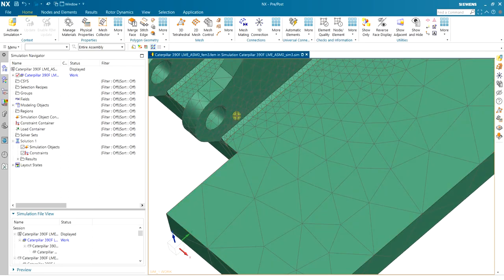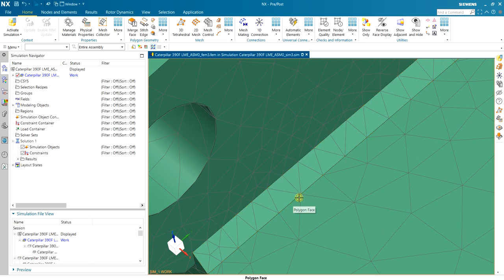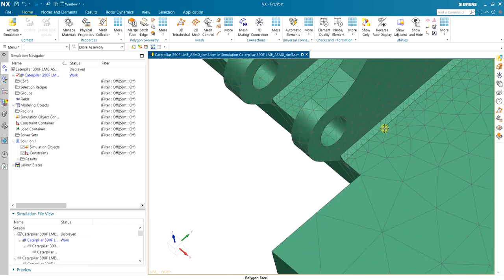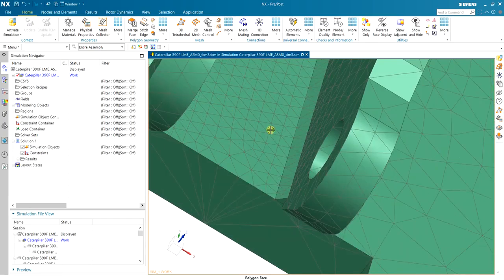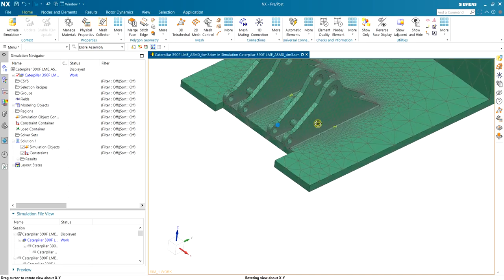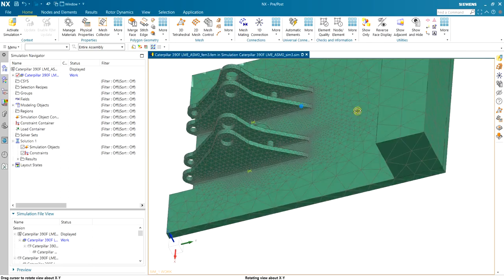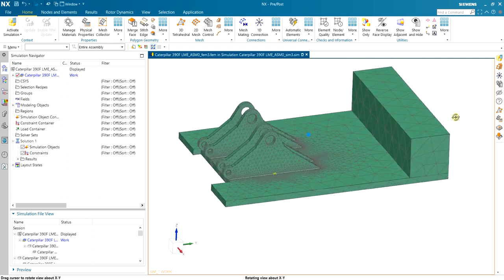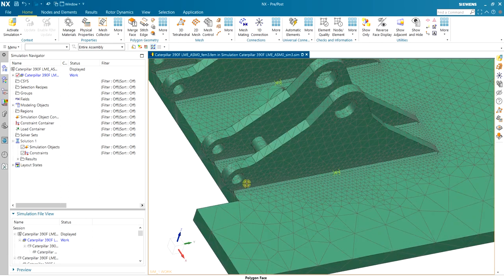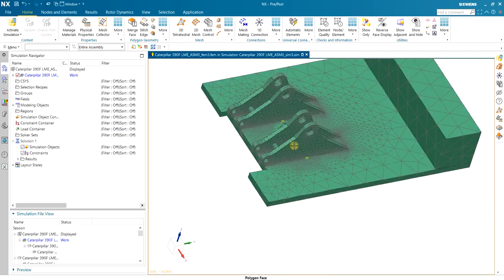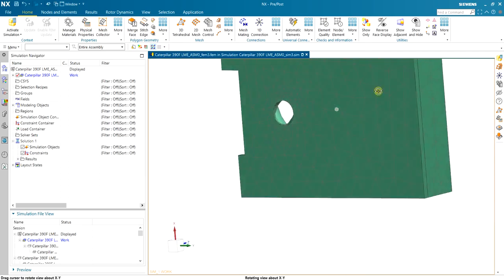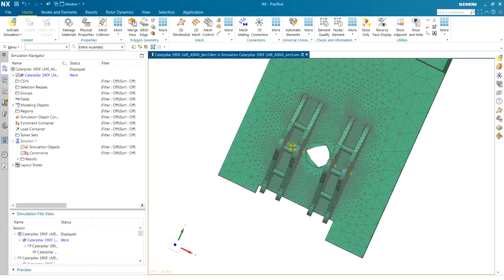Now you see that near the places that we needed mating, the elements are aligned to share a node, so the mesh can mate on each face. And also the size remains big for the parts that we don't need much detail, but it's getting small around the weld. This mesh seems okay, except at this point.